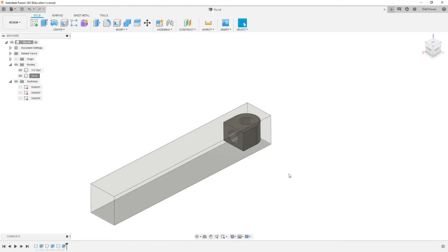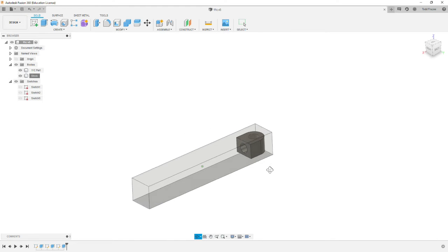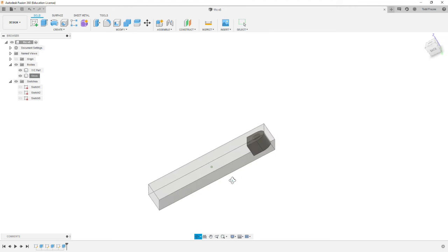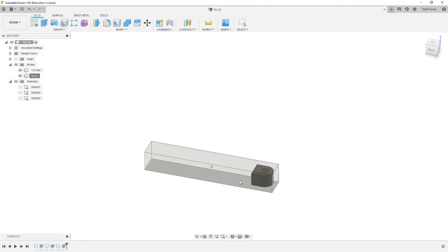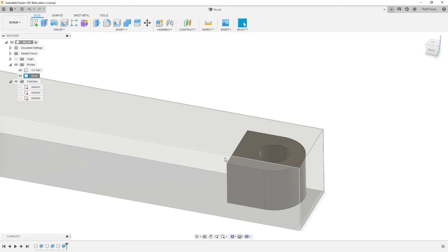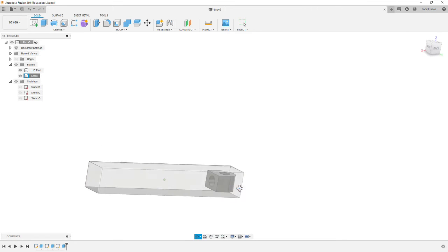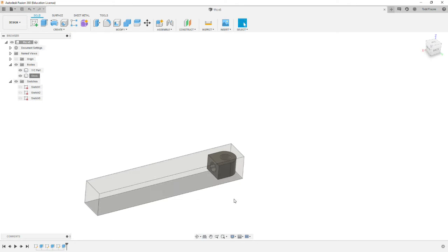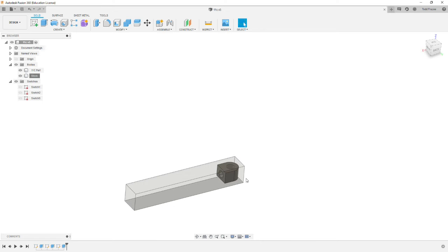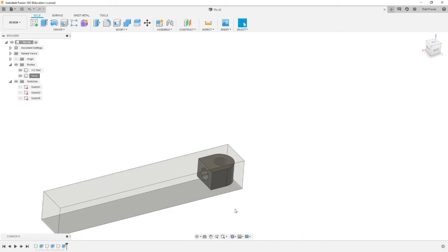Okay, now planning ahead that we're going to machine the model, but that we need to machine outside of the model to part the material off, we want to make sure that our cutter is coming clear and past. One method to do this is to create a sketch to drive toolpath around. You don't have to, but this is one method. So I'm going to show you how to define a sketch to drive toolpath across.